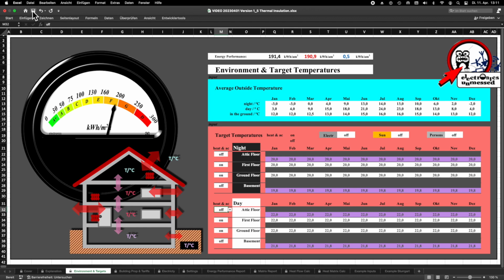It is interesting to see that the energy efficiency values become worse with fewer floors. This actually makes sense because the ratio of exterior walls to living space is bigger then. As an effect of this, the energy consumption per square meter increases. Probably each of us expected such an effect. But could you have quantified this effect before? By the way, the insulation from the ground floor to the earth ground is rather bad, which has the biggest impact here in this example.